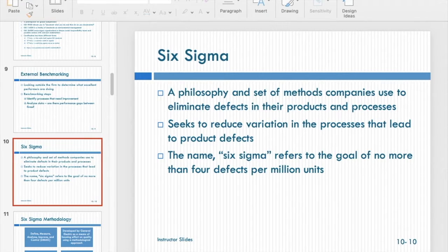Okay, so if we set up this range for the firm, and in the production process, let's grab some sample and calculate the standard deviation, all right. If this range can include a total of 6 sigma variation within this certain range, we say, okay, probably the quality of this product is already good enough. Okay, so what is meant by 6 sigma?